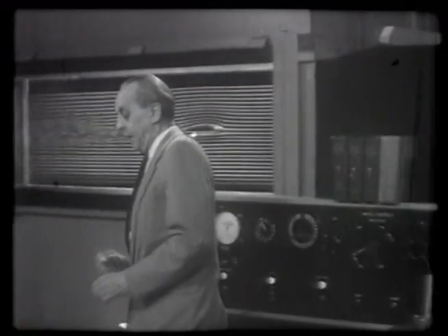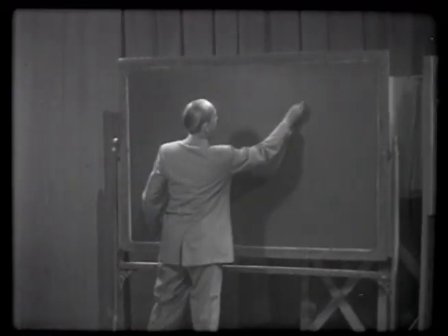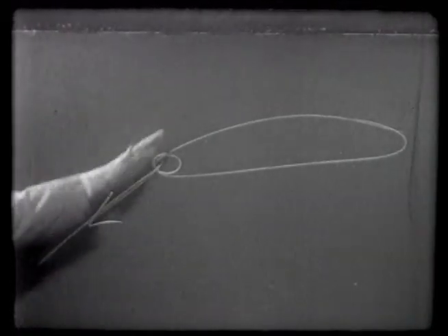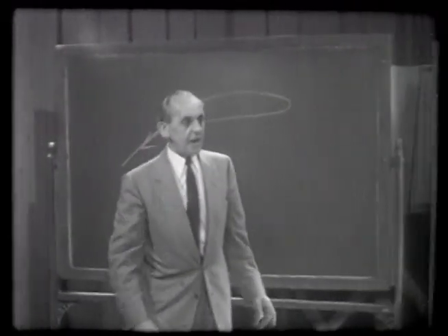Now you see this blowing has the advantage that you can lead the air to the blowing slots through small lines, and in this way it saves space and has a much more practical application. Now you don't need the blowing just for making high lift, but you can also make kind of an invisible flap by blowing out at the rear end of the section. That's what they now call a jet flap, a section where here is the tube in it and we blow out this way. And this layer of air then works like a jet flap, as you see it here.